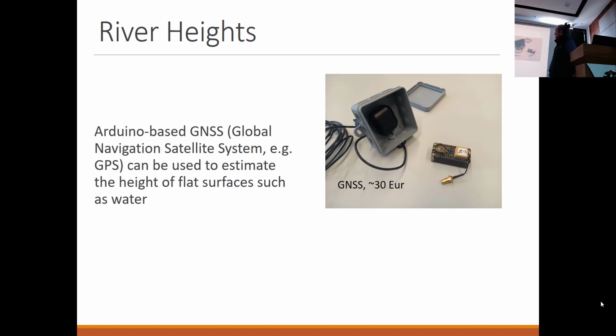The first is that GPS has a clock. So if you have your data and you're away from the internet and your computer or your Raspberry Pi is turning off very often, it doesn't always remember what time it is, right? If there's no battery and it turns all the way off, it starts thinking it's 1970, right? It goes to this default clock. So the nice thing about GPS is that there's a clock. Every time you get a GPS signal, it tells you what time it thinks it is. That's part of how it works, how far away in time different satellites are. So that's one useful thing, to keep all of our sensors on the same time syncing.